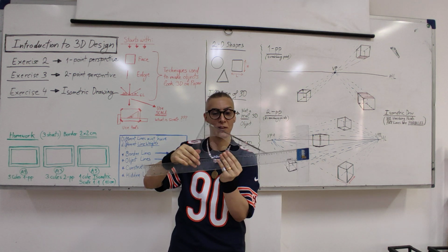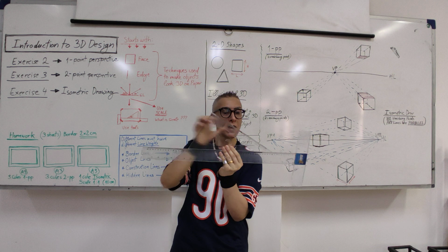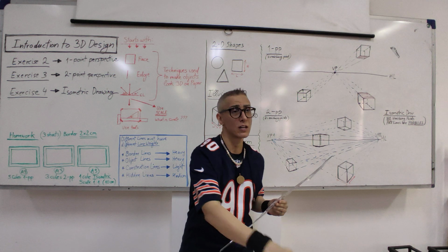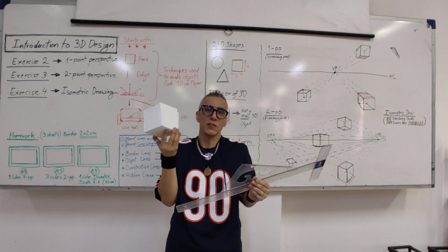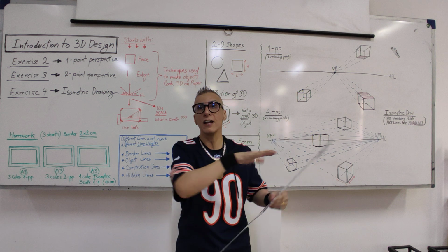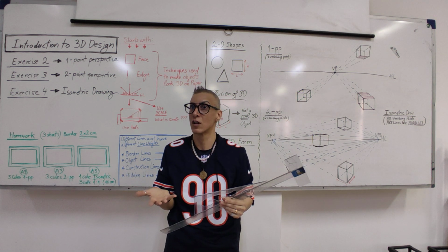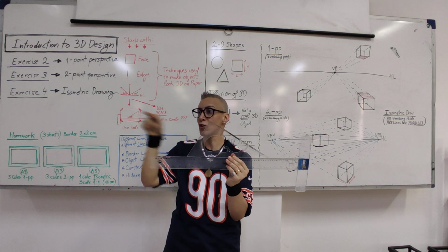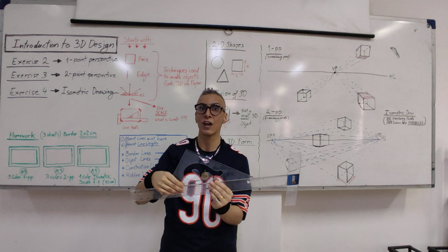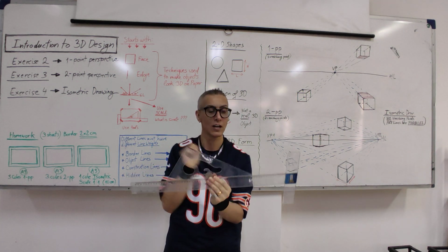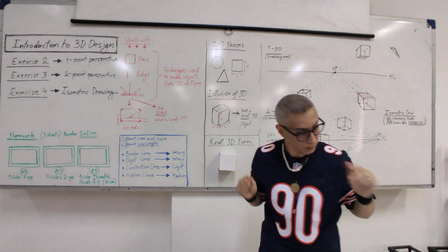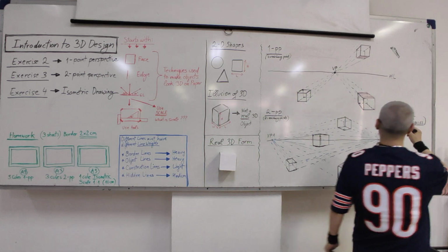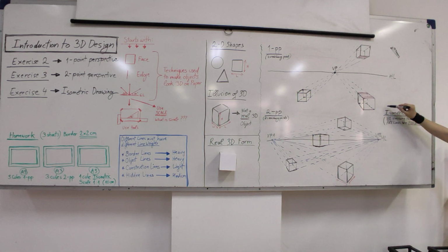Which is the 30 degree? This is the 30 degree. So the lines that you will draw will have to be at 30 degree. Now, because we are doing one cube, it's very simple, but later when we draw the entire composition, the model, there will be a lot of 30-degree angles, okay? So you have to move this around, draw many lines, then go up, draw more lines, and all of them have to be perfectly at 30 degree. So the isometric starts with, okay, here is space dedicated for it.